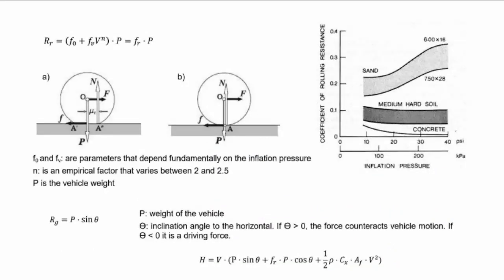And then next one, rolling resistance. What is the rolling resistance? Rolling resistance forces are due to hysteresis in the tires. This resistance counteracts thrust force and its value depends on the vehicle mass, steering geometry, profile, type, and pressure of tires, driving speed, surface, and state of the road. It's calculated by multiplying the normal load on the center of each wheel.